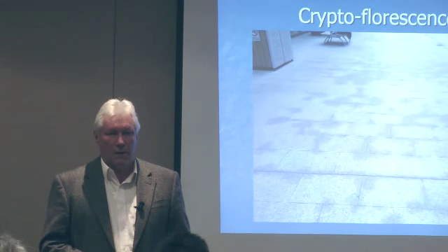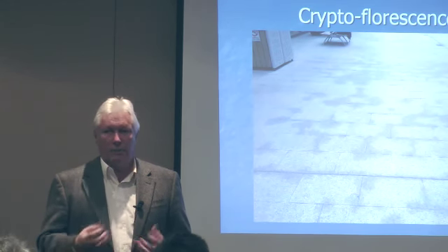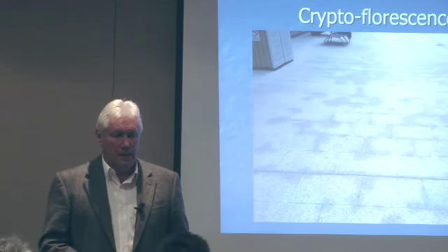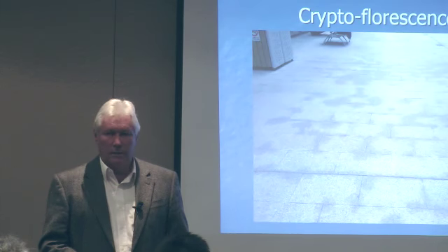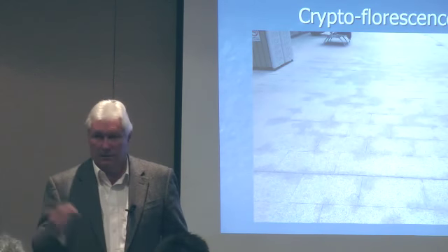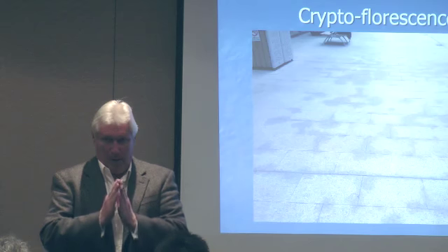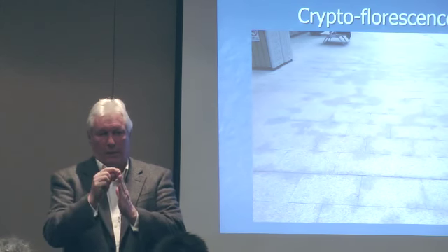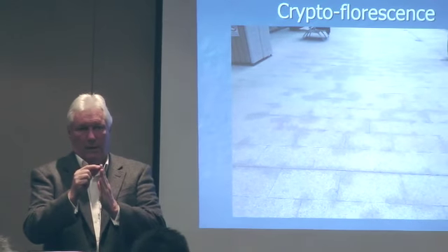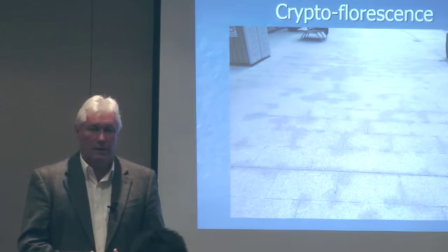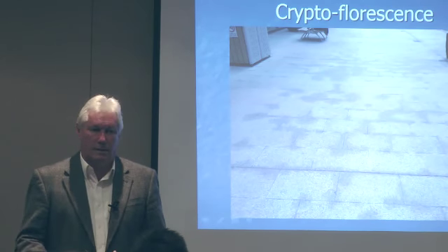Happening quite a bit with exfoliated granites. Exfoliation blows open a fair amount and fractures the surface of it. It's a flaming process, so we've got more shattered edges and it's places where product can get in. And when we've got marble, which we can get off with acid, no problem, we can get marble basically forming in those tight cracks. But when we put the acid on and eat the marble away on the top, we can't leave it there long enough to get all the way down through all the cracks to get it out. So we just can't do anything except replace the offending tiles in most cases.